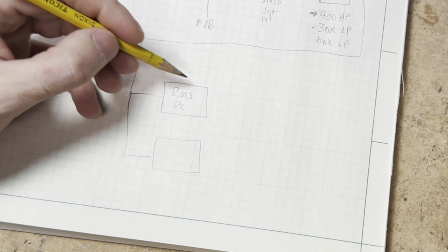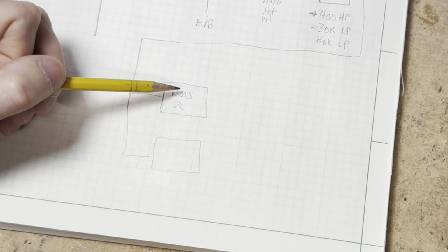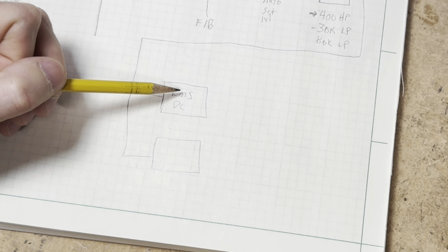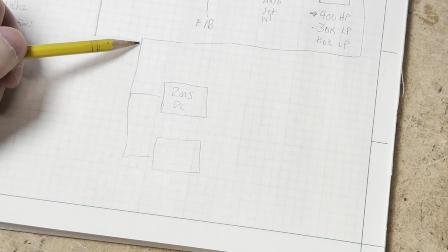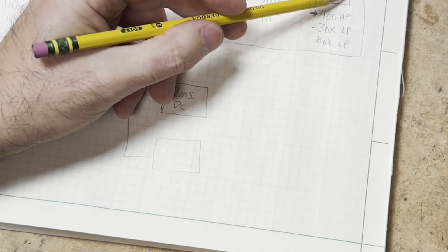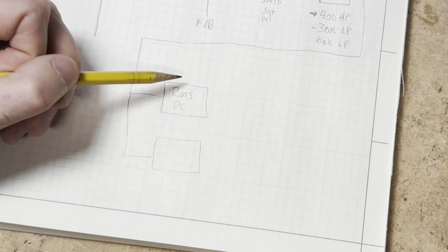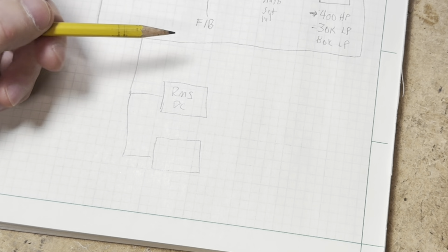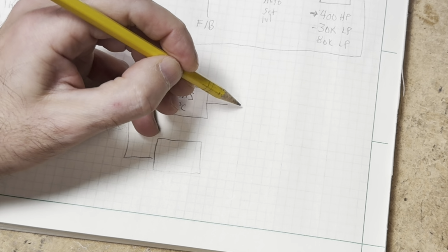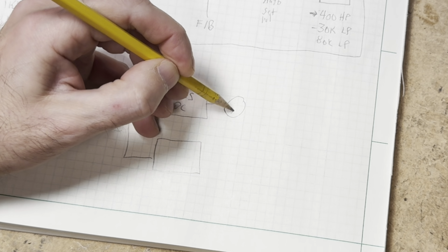And this is probably the more accurate way of doing this measurement. It's going to take whatever AC components, add them all together and convert them to a DC value. Then that DC value can be displayed on a panel meter.